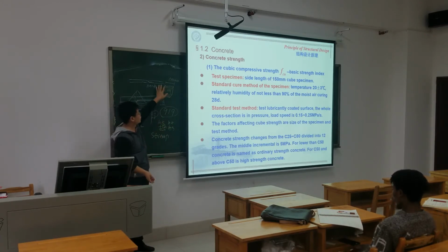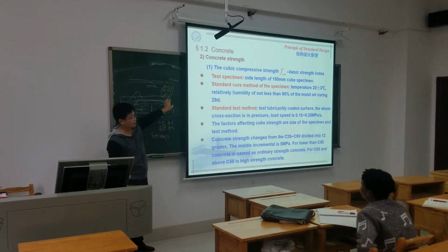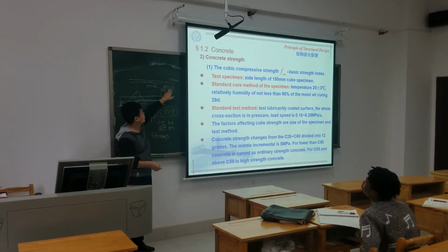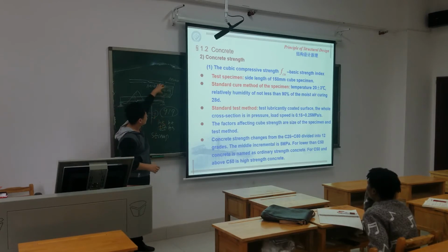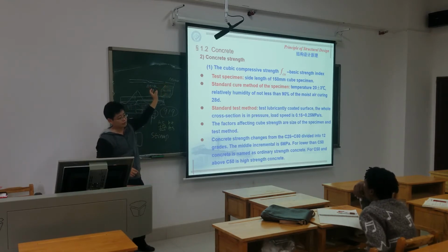If you don't put oil or lubricant, maybe in the middle it connects with the bed tightly, and the edge doesn't connect so tightly. So finally, the force may be concentrated in the middle, and the result is quite different.